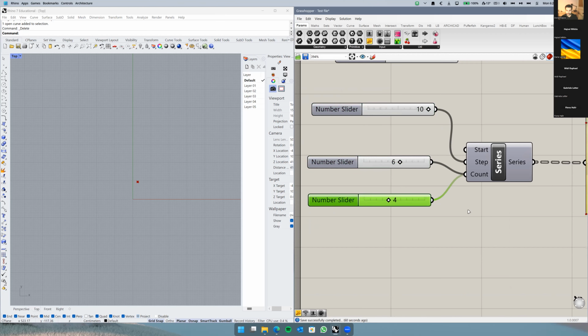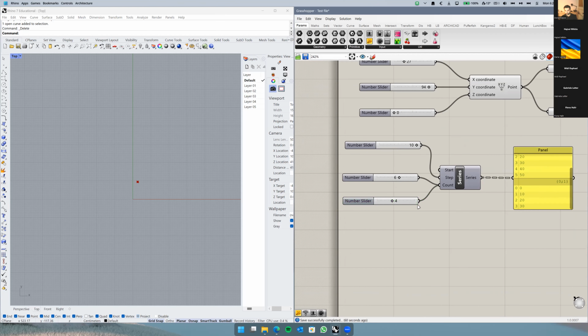Yes, sorry. Like I said, basically when I connect something, it disconnects the other one. To connect multiple ones, I start dragging. While I'm holding my mouse button, I press and hold Shift and connect. So this time I can connect multiple items to the same input. Note that not every component allows that. Some components break when you add multiple inputs into one input port.